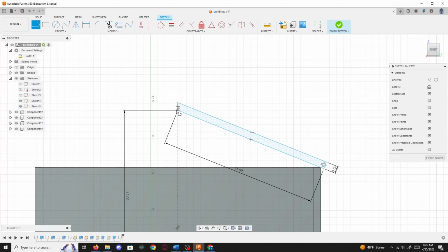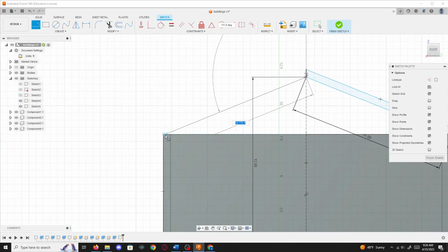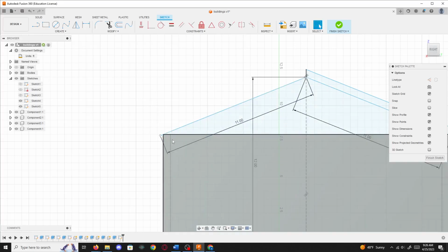So start at the tip of your construction line, snap to your side, and then instead of leaving it how it is while it's sitting there, press 11, and then hit enter or click. If I hit enter, it deselects my line tool, but it places the line where I want it. So I will reselect my line tool, come up, and if you look right there, this square that appears where my new line is being formed, my old line was, shows me that it's at 90 degrees, and that is what I want. I will hit 0.5 for my thickness, click again, and snap to this point.